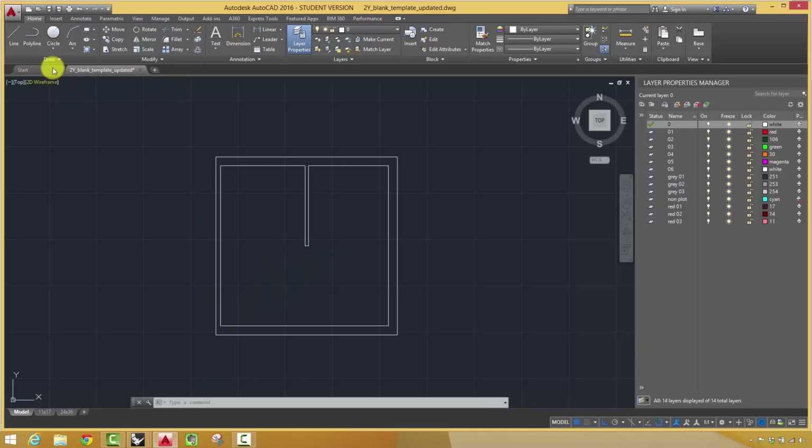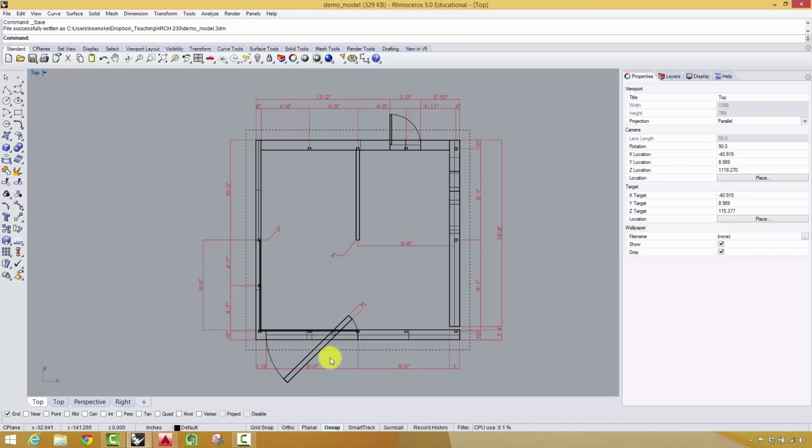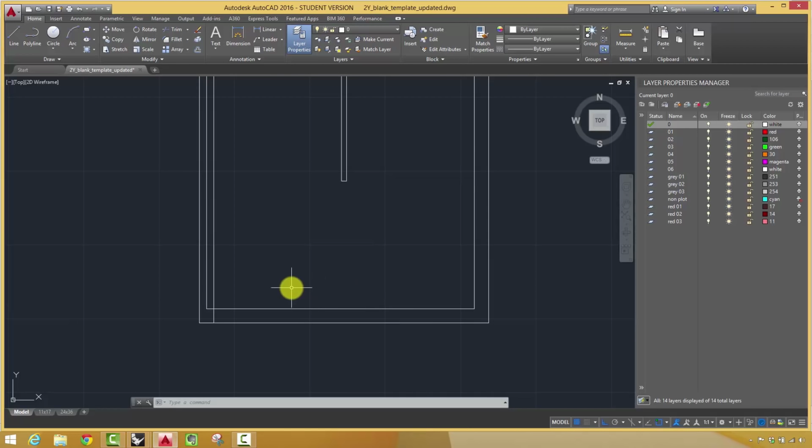Okay, so 2 things. So the first one is going to be, and see, once you've got the space set up, you can start to do things like you don't really measure things. You use other objects to derive the placement of other objects. So I'm going to offset the one wall a foot, and that will create this line that I need, right? And then I could offset this 9 feet, or I could offset this one 10 feet. Since I'm already here, I might as well offset that one 9 feet. So I'm just going to go ahead and offset 9 foot.